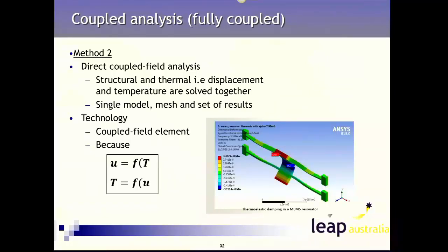So you can get into the situation where you have a structural model whose time step is dictated by the frequencies you want. That time step is too small and results in temperature oscillations in your thermal analysis. That generally won't happen for a MEMS type device, but if you did try to simulate both of these physics at once in a larger structure, it's highly likely that you'll run into that scenario where your structural time step is too small for a stable thermal solution. So that situation sort of takes care of itself, because you don't need to do it.